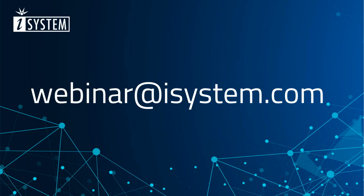So thank you, Otton, for this good insight into how to profile a bootloader. There were some questions coming in, and some interesting ones I will simply ask you. Number one is: Is it necessary to have a trace interface like HSSTP available on the ECU, or is it also possible to store the STM trace data on chip in some sort of buffer?